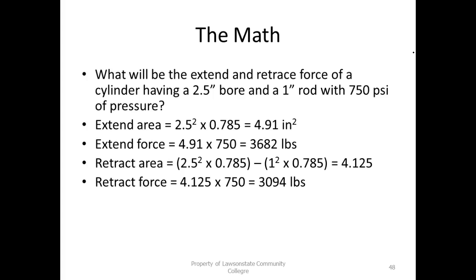And we have a problem with air too. What's the problem with air? Well, all air has moisture in it. And of course, the amount of water air can handle depends on the volume of the air. Right? You understand that? So when we start compressing the air, we decrease the volume. What's it going to do with the water? It can't hold the water anymore.